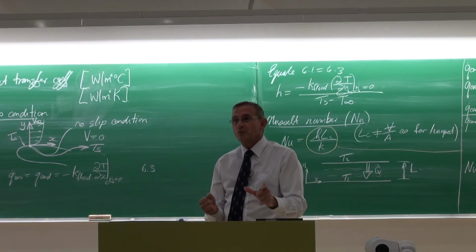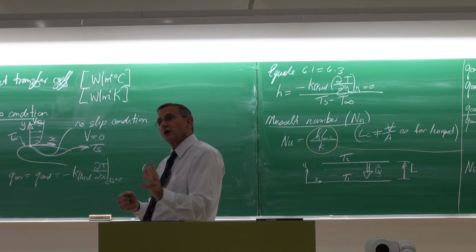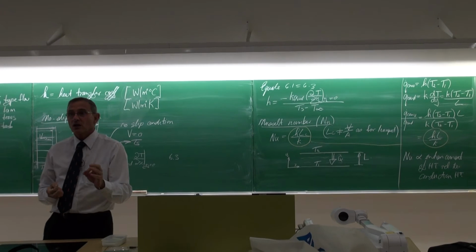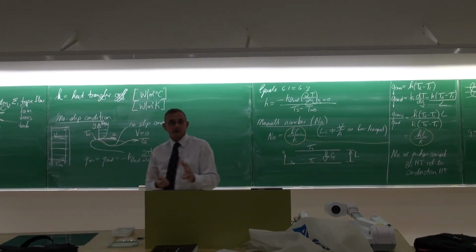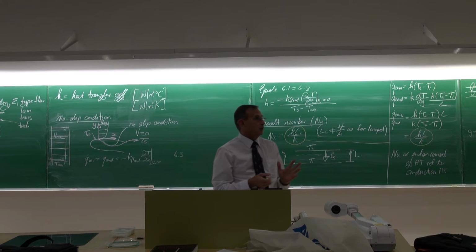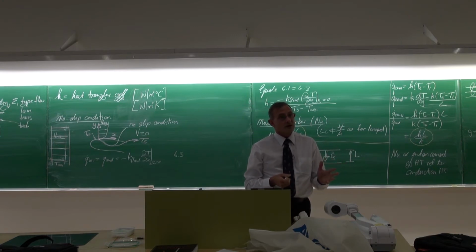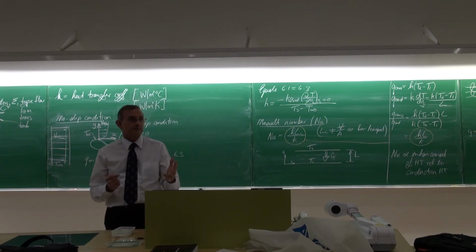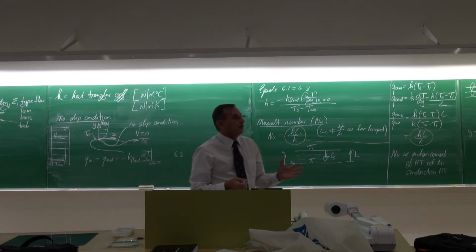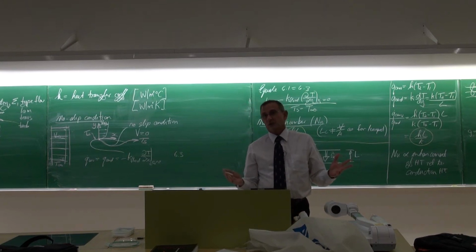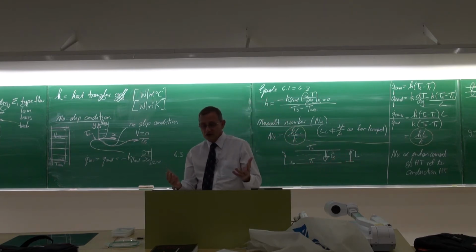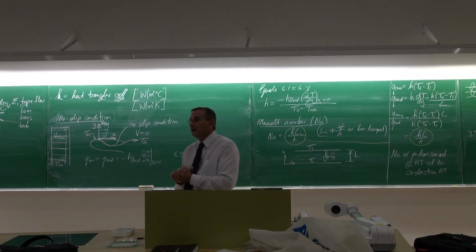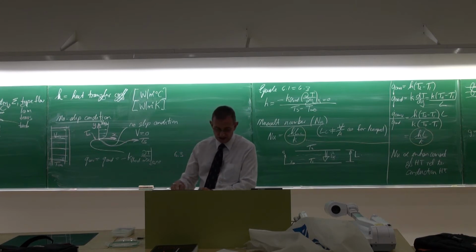Compressible versus incompressible flow. Can you remember when the flow is compressible? Flow is compressible when the Mach number is larger than 0.3. How do we determine the Mach number? The velocity divided by the velocity of sound. You remember? Normally, water is always incompressible. I think you've already done it in thermodynamics, and that would also be the assumption that we will make in this course in most cases.